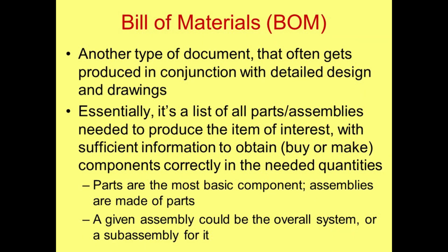Okay, so another topic I want to briefly touch upon is bill of materials. For any mechanical or electrical aspects of a given design, the designers will often prepare a document known as the bill of materials. This is essentially a list of all the components that are needed to make the design being specified, with sufficient information that would be needed to obtain all of the correct components in the correct quantities.